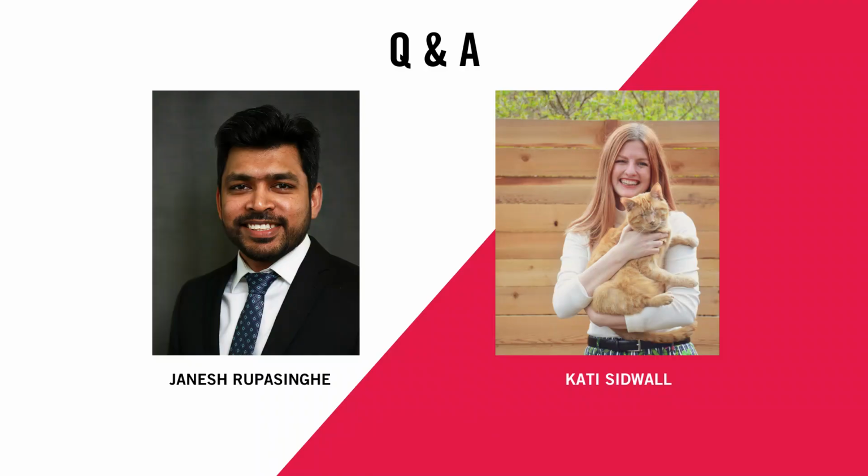Okay, so let's go to a couple of questions about these models. Janesh, we have a question about whether the fuel cell is a static or dynamic model. Do you want to talk a little bit more about that? Yes, thank you, Kathy. This fuel cell is a dynamic equivalent model because this equivalent circuit consists of an ideal voltage source and 3 resistors to represent the cell. Each resistance and this voltage source are calculated in each time step.